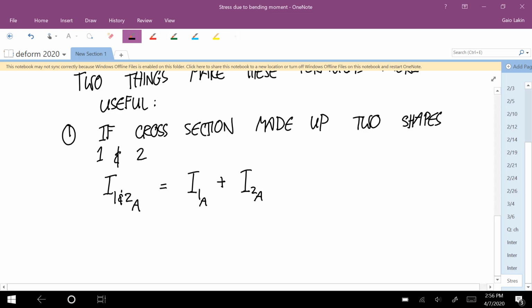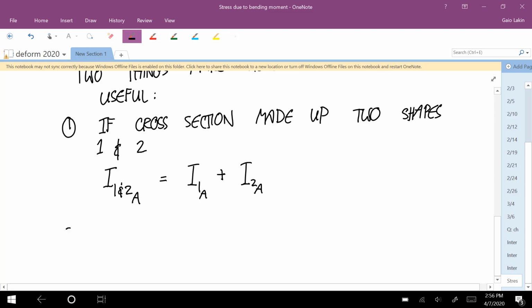So what we need is a way to use our calculation of the area moment of inertia of the simple shape about that simple shape's centroid, and then move the axis to some vertical distance from there. In dynamics, with the mass moment of inertia, we do that with the parallel axis theorem, and it turns out that we have a parallel axis theorem for this too.